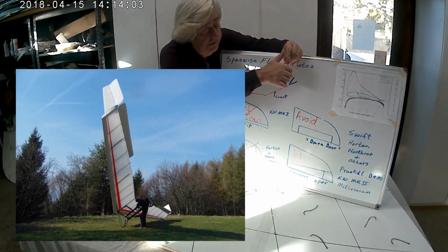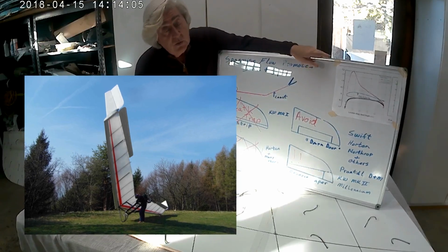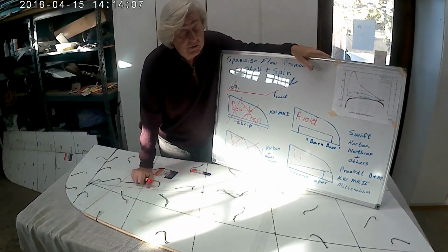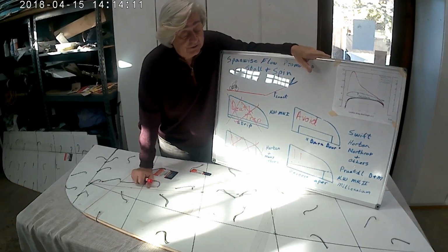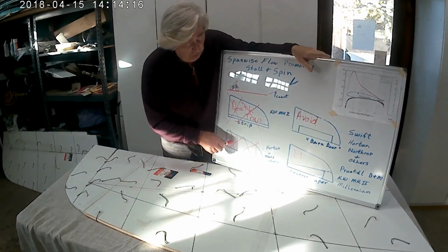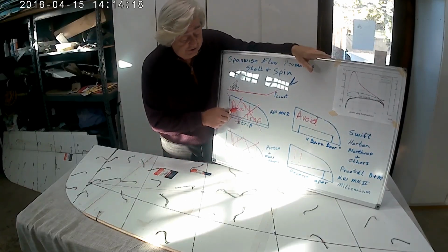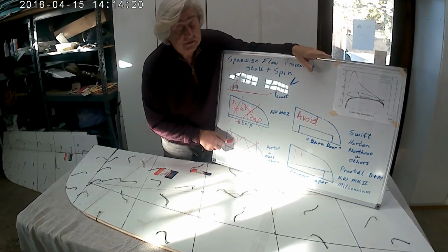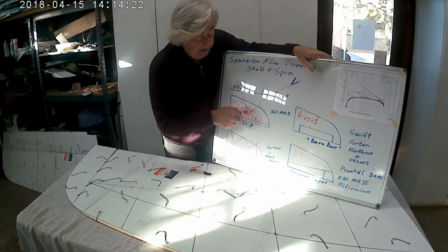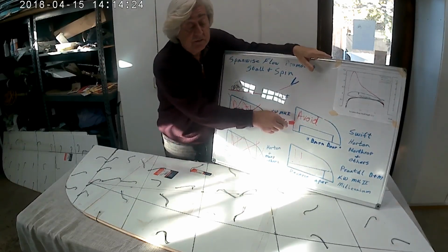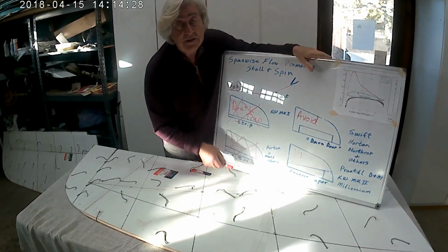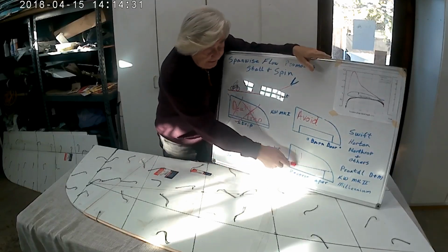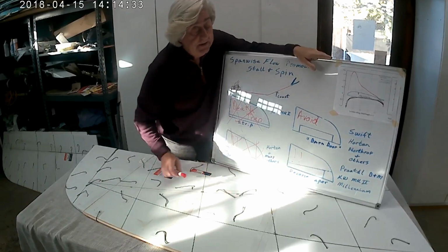So that said, if you're doing a swept flying wing, reverse taper elevon is probably your best answer. How much? I don't have an answer for you there. But we do know that there are some death traps out there that you should avoid at all costs. Probably three of them, and these are all conventional. So the conventional answer that we use on aircraft is wrong for flying wings. This is the right answer for flying wings.